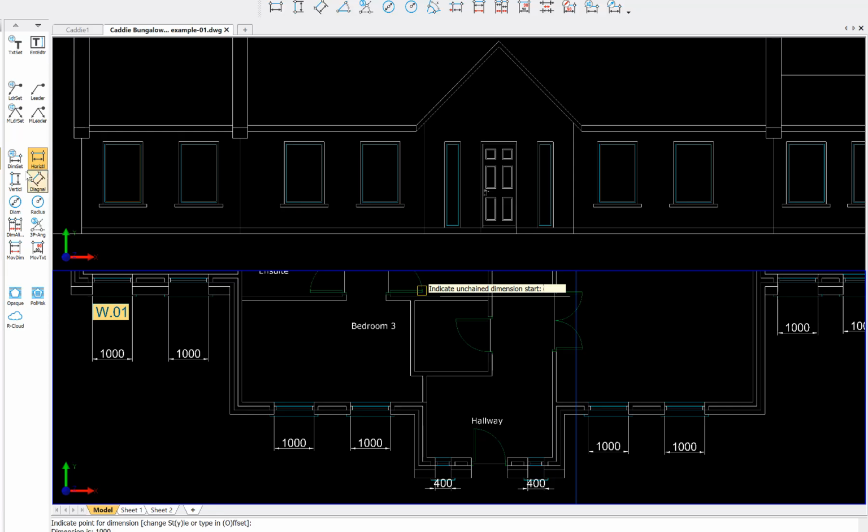So now we want to dimension them vertically because we want to know how tall they are. We could, of course, just measure these, but here we're actually recording it onto the page such that it's an easier reminder. We're not having to go back and do it again and again. So we're dimensioning in the elevation. So we click into this viewport and we can see there's a blue box around this one. And it will say, OK, we're going to dimension from there to there.